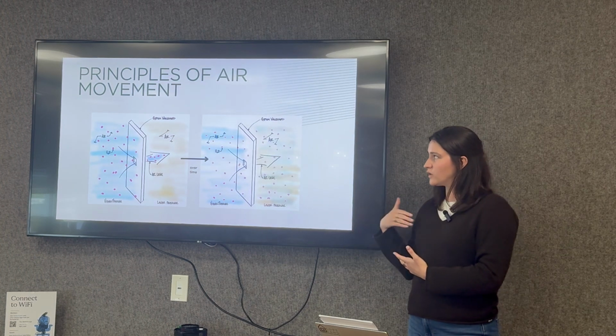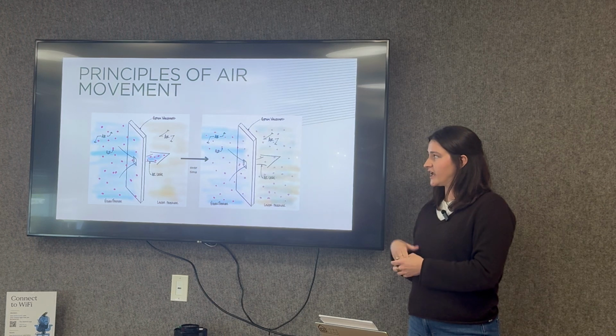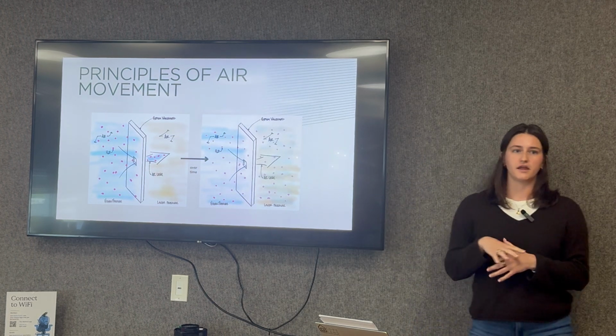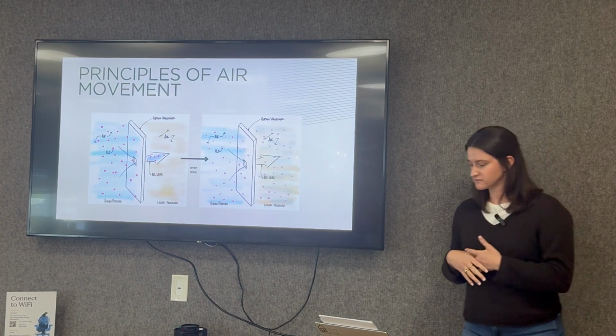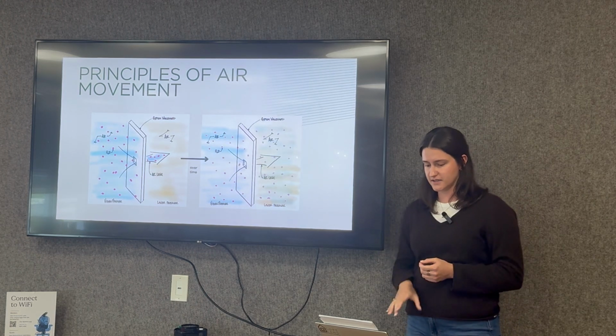going to move. And what can be so detrimental about air leakage is that air can carry whatever's in the air along with it, like water vapor. And airflow has the ability to move a lot of water very fast.